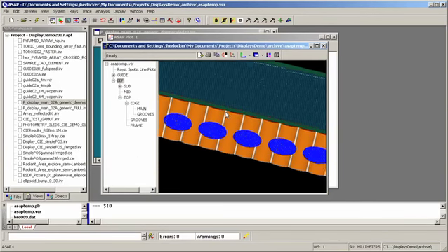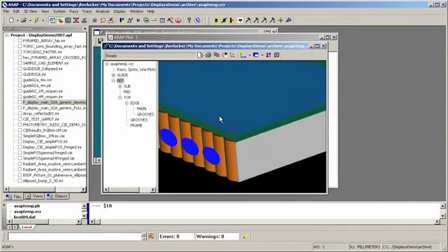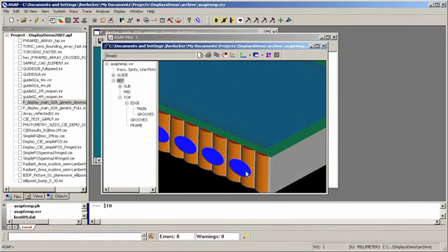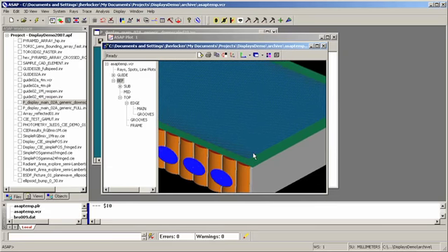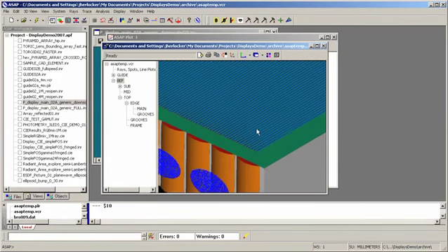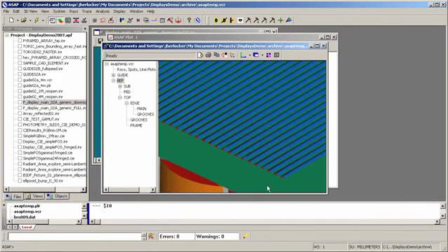What we have here, let's take a look at a corner so that we can really see the structure. Remember, these spots are the spots that show the point of origin or the plane of origin of each of the LEDs that we're using to illuminate the light guide. We have little cylindrical lens structures on the edge that couple the light into the guide. And then, we'll really have to zoom in to see these well, we have little ridges that stand up above the surface, and these little ridges are cylindrical ridges which cause the light to cross-couple.